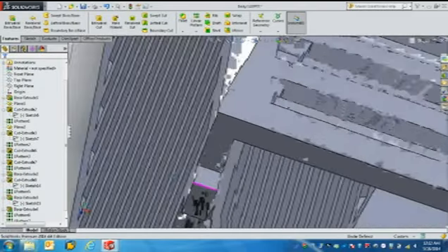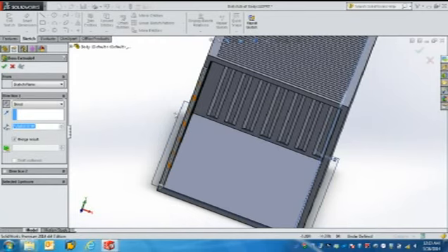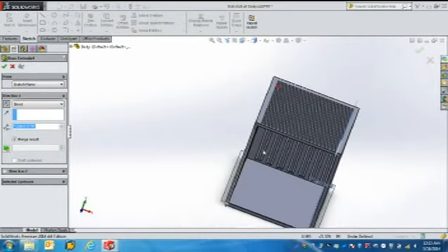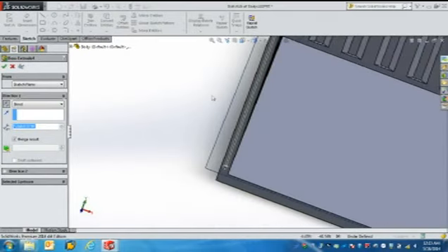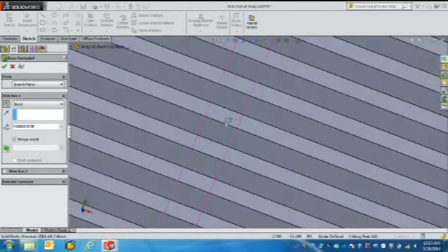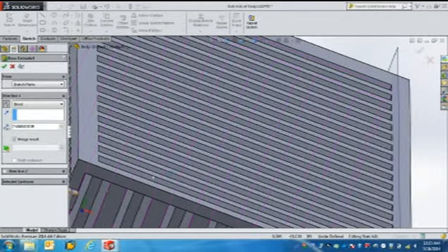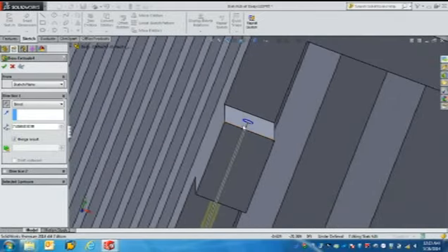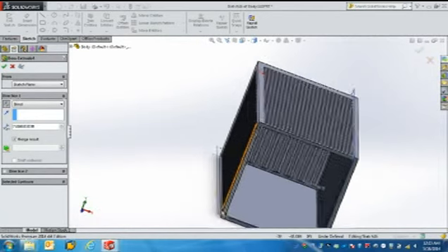Well, what I have done here, I have simply drawn a rectangular hinge here, and the second step, I will draw a circle on the surface of this hinge, and I will simply extrude it to the base. Now we will utilize this rod structure to attach the door with this container.